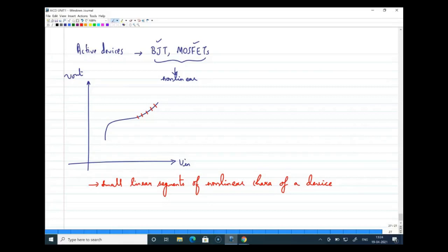From the characteristics of both the devices, you can see that the curve is non-linear, but we are designing amplifiers out of BJTs and MOSFETs, and we do have faithful amplification out of that. The meaning is then those amplifiers are working as linear amplifiers. So how do we achieve that? If you can remember, we would say something called the Q point or operating point, and we will also specify the input amplitude. So definitely you would have observed this in the lab. Even though you had a 1 week lab, you will definitely remember.